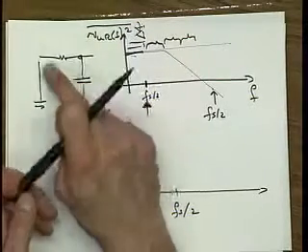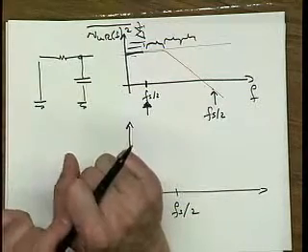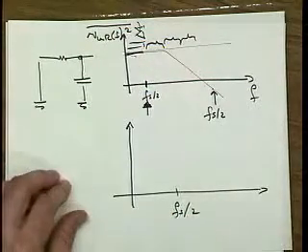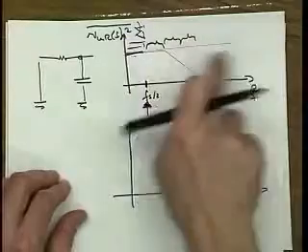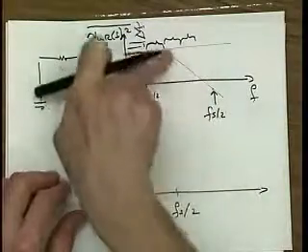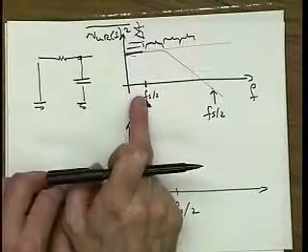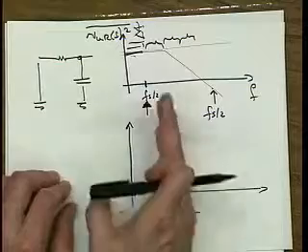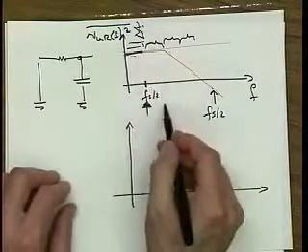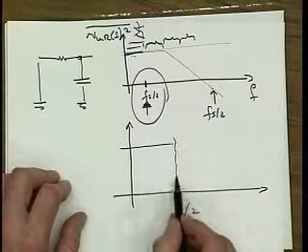That means that this RC thing has to be very fast. In other words, it's got to have a time constant that is way out there, way faster. So in other words, 1 over this is the time constant of the circuit, right? That better be fast compared to a sampling clock period. Okay? So most of the time we're going to be in this situation here. And then the noise really is white.